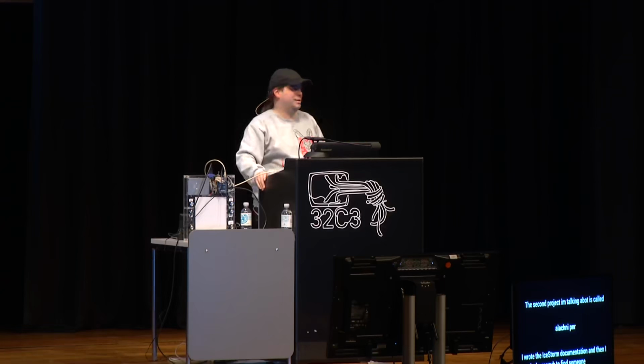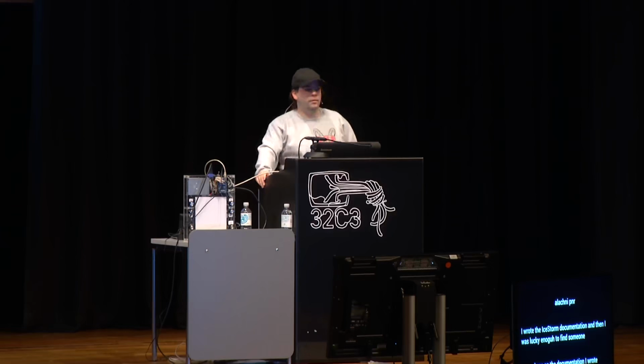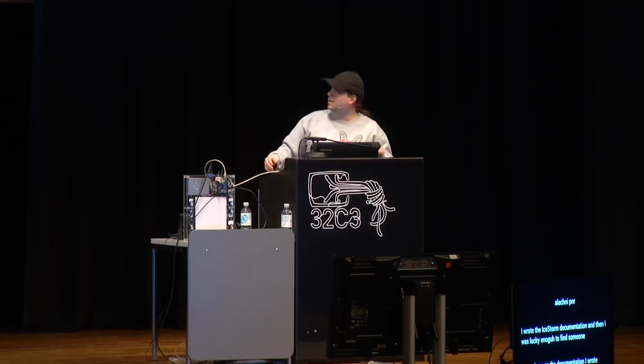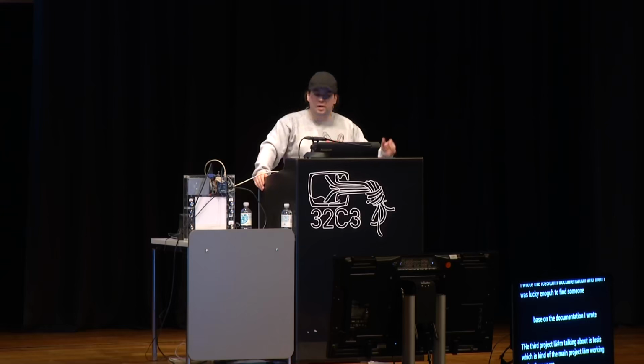The third project I'm going to talk about is Yosys. And Yosys actually is my main project that I'm working on now for a little bit over 3 years. And Yosys is a huge project, but simply said, it's a Verilog synthesis suite. So when you have hardware designs that are written in Verilog, you can use Yosys to synthesize those designs to netlists for a variety of different architectures.